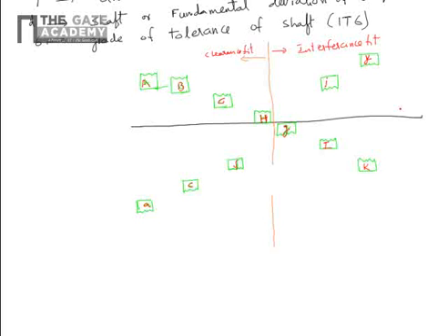Even if you look at this basic size line, the values of holes are on the upper side of the basic size line in clearance fit, and they go downside of the basic size line in interference fit. That means the hole size is bigger than the shaft in clearance fit. Similarly, the hole size is smaller than the shaft size in interference fit. It's simple.